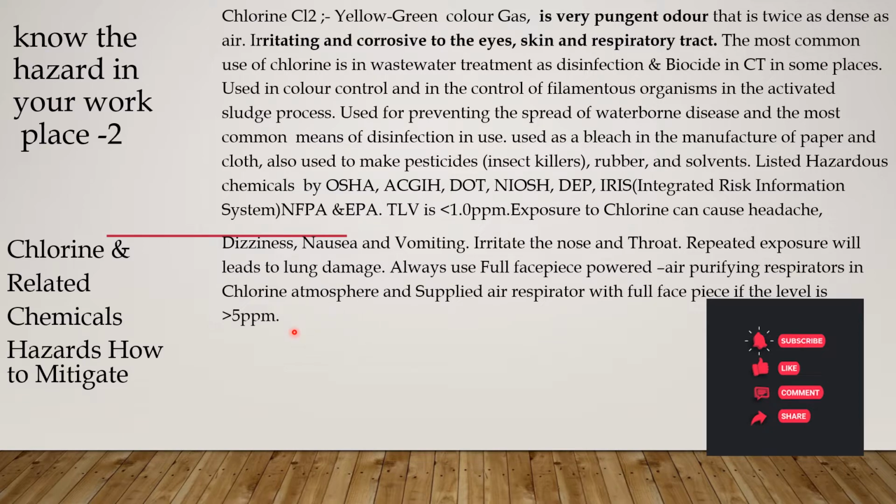And if the leak is continuous in the chlorine plant or sodium hydroxide production plant, where chlorine is also a byproduct, there we have to use the full face piece with a supplied air respirator.